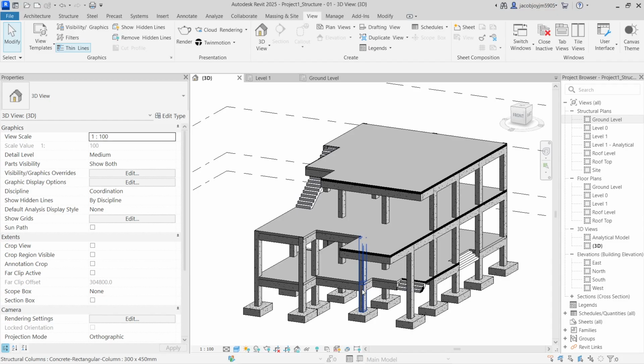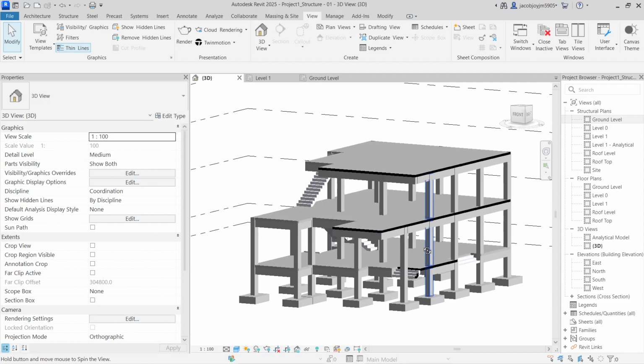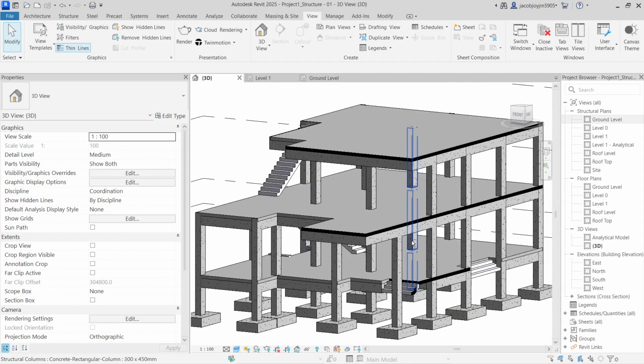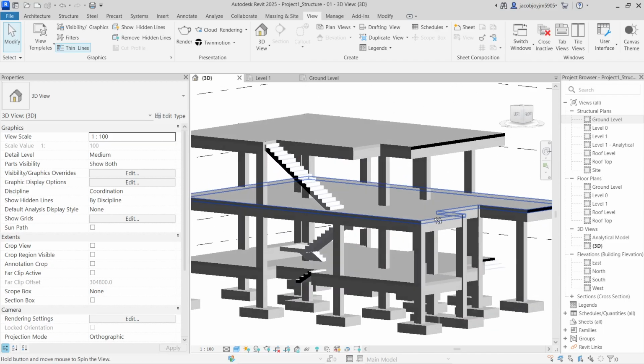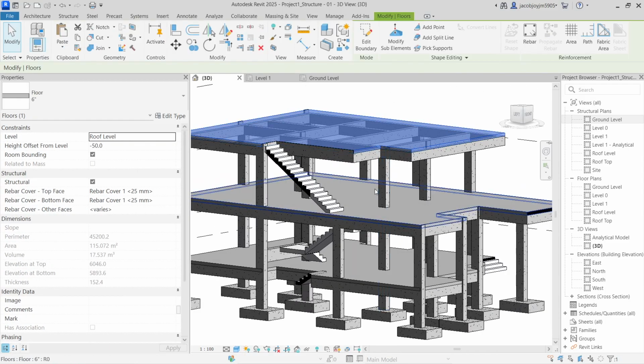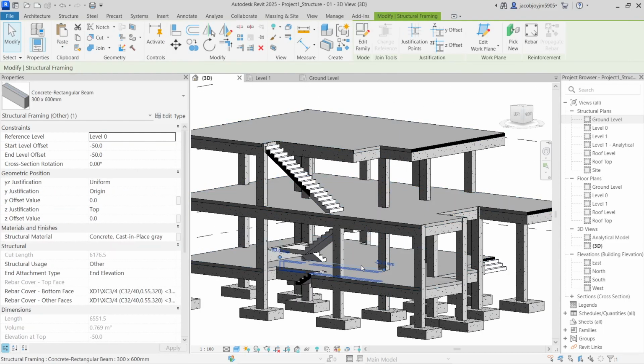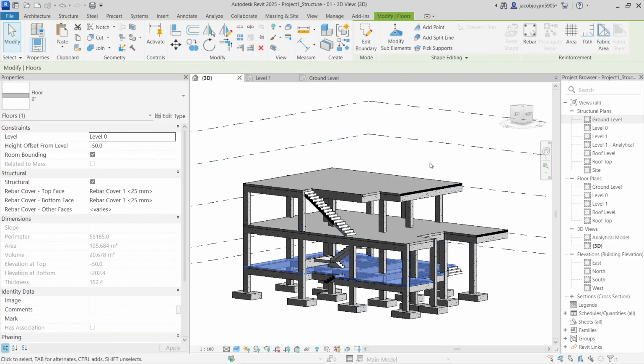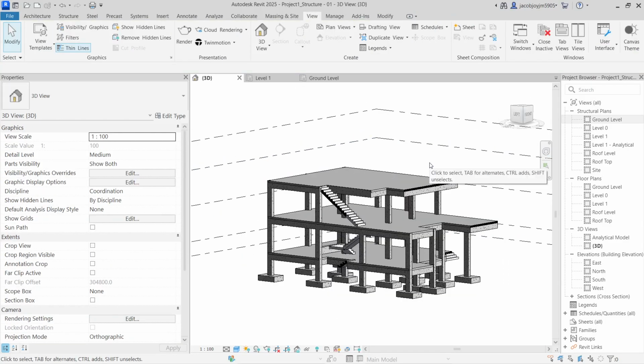To create a framing plan, let's take that into another video. Today I'm just showing you how to model the structural model. That's it. The step is very important. You are creating a structural model for the architecture intent model. So when you're creating a new model, select the template and then link the architecture model,